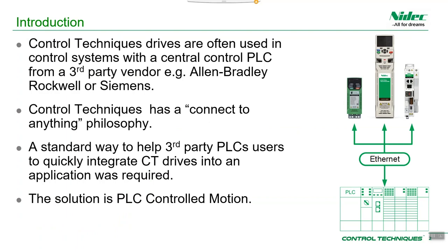So Control Techniques drives are often used in control systems with a central control PLC from a third-party vendor, something like an Allen Bradley Rockwell or a Siemens PLC. Control Techniques has classically had a connect to anything philosophy, so we've supported lots of third-party vendors' communications protocols, things like Profinet, Profibus, DeviceNet, Ethernet IP.